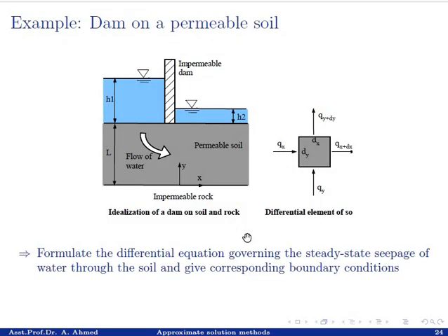Let's take another example and try to develop a mathematical model for this particular problem: a dam on a permeable soil. Formulate the differential equations governing the steady state seepage of water through the soil and give the corresponding boundary conditions. Again, the procedure is the same. Take a small differential element in the permeable soil of length dx and dy.